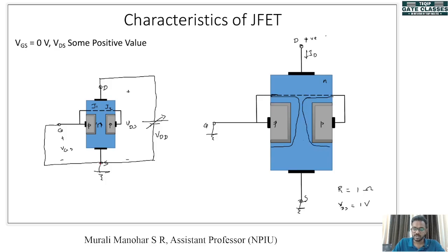So our junctions will look like this, and in here also, in the p-type material also, the same happens. So this is the width of the new junctions. This is the width of the junction when we apply a positive VDS. Okay. Now let's say when VDS is low, this width is low. When we increase the value of VDS, this width will start to increase. So if you look at the figure, you can see that at a particular VDS, this and this will collide.